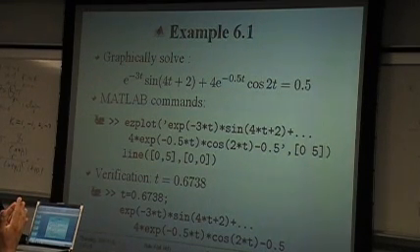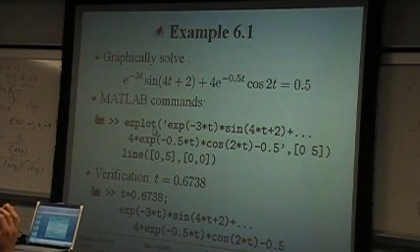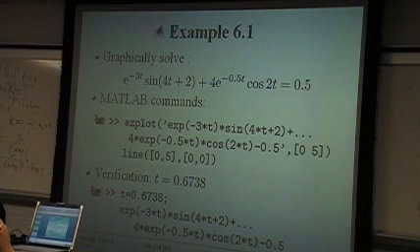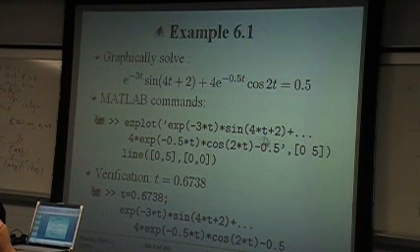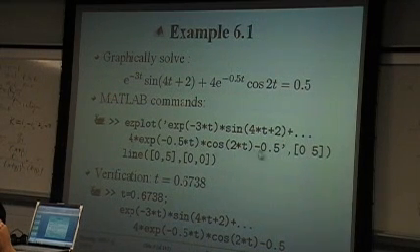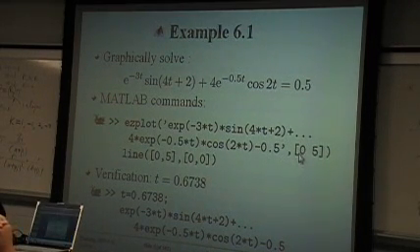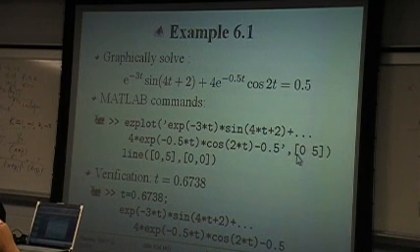Alternatively, we can use the ezplot function, and we can solve the problem easily by calling it. Here we can specify the original equation first, quote the original equation, and specify that we can draw the curve in the interval 0 to 5.